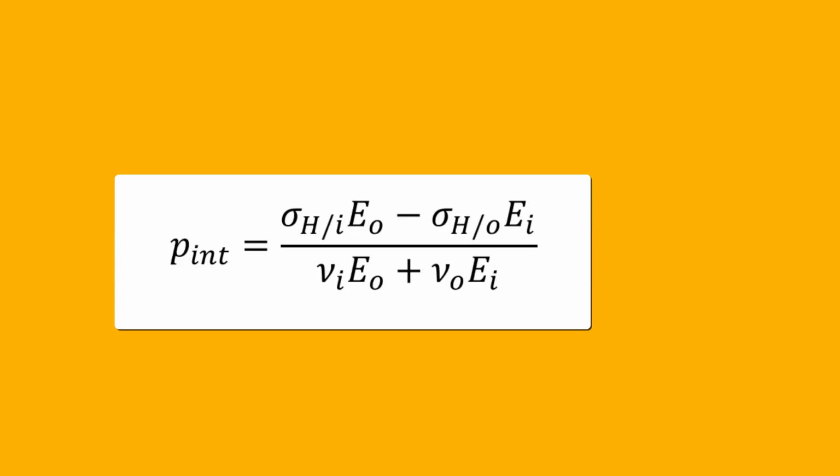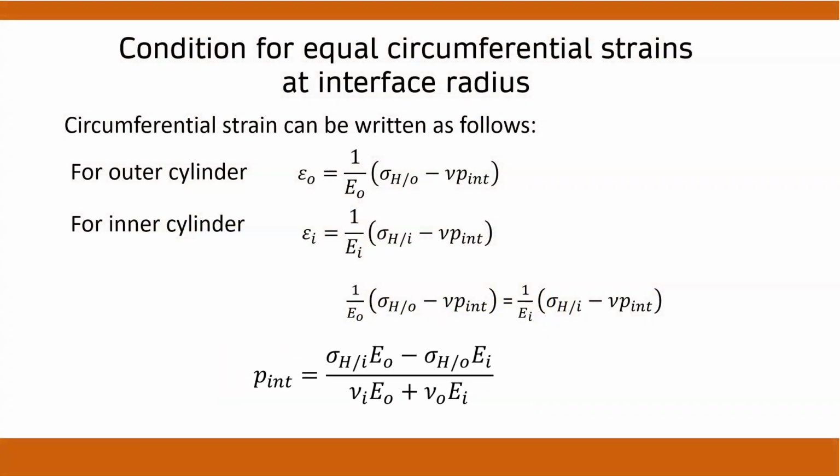The other equations have to be derived using the plot of stress lines we have already constructed. We require 3 more equations, as we have 4 unknowns, namely interface pressure, 2 hoop stress values at the interface, each for 2 cylinders, and the value of x in the plot. The x is the intercept on the horizontal axis for the stress line corresponding to the inner cylinder.